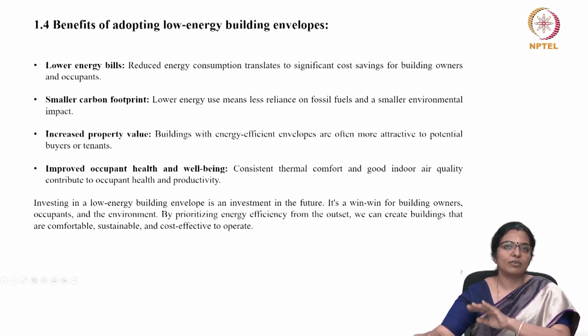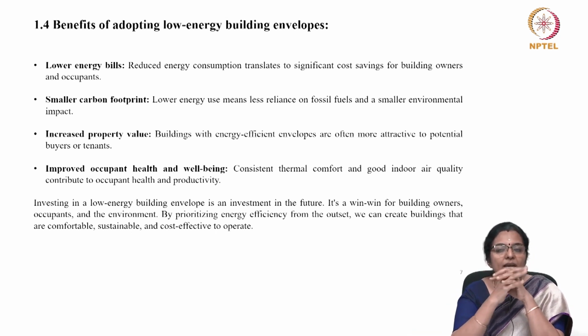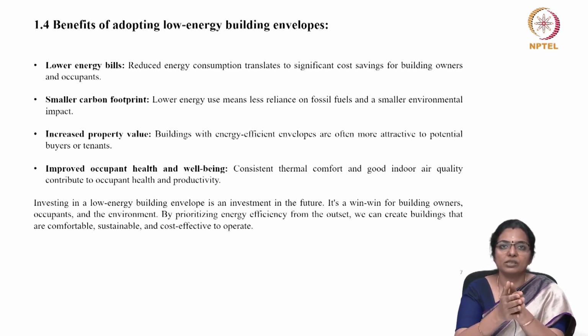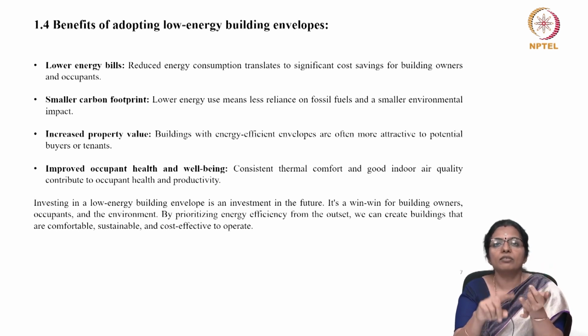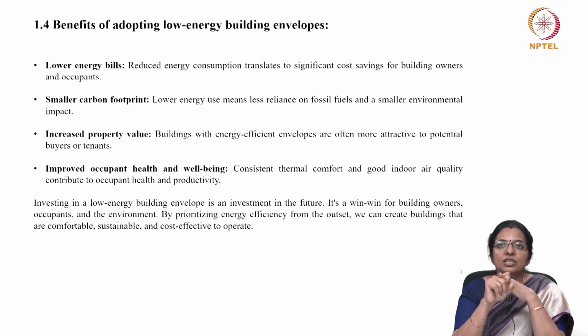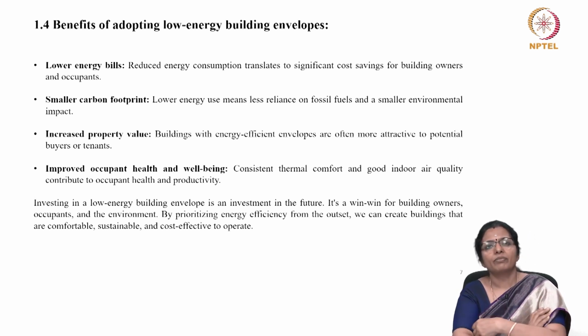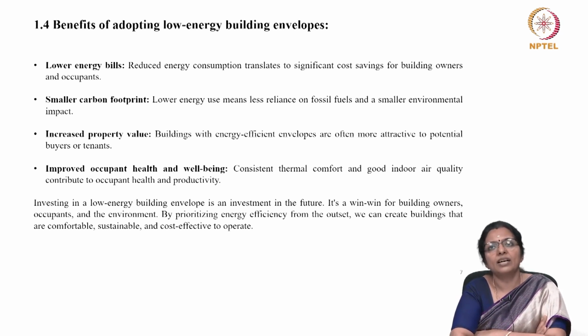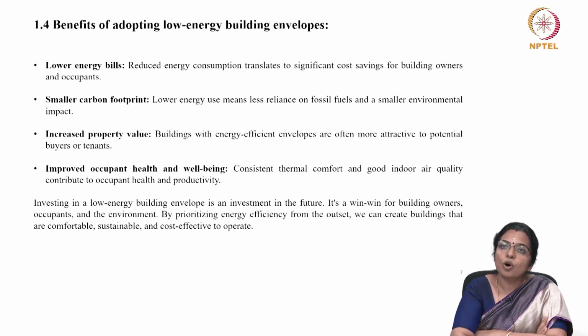Let us see the benefits that we could have by adopting low energy building envelopes. Low energy building envelopes are less expensive because there is reduced energy consumption in order to increase the comfort of the user. When I say comfort, two kinds of comfort: thermal comfort as well as daylighting. So, the reduced energy consumption leads to lowering of energy bills. The overall carbon footprint of the building gets reduced dramatically because lower energy use means we will have less reliance on fossil fuels, and therefore our reliance on electricity will get reduced, which will result in low operational energy and therefore low operational carbon, resulting in smaller environmental impact.